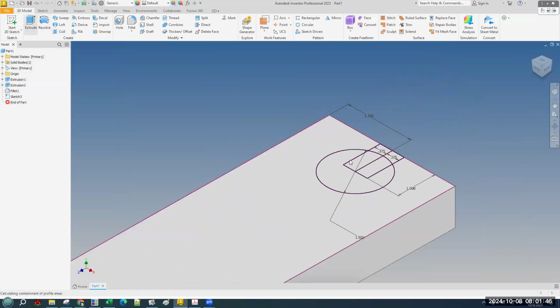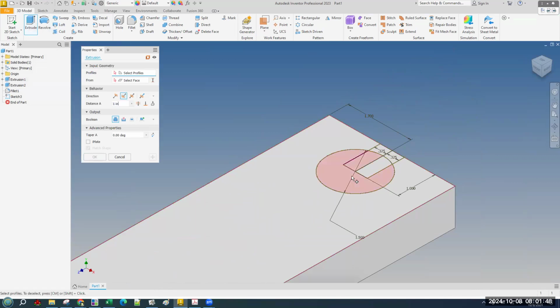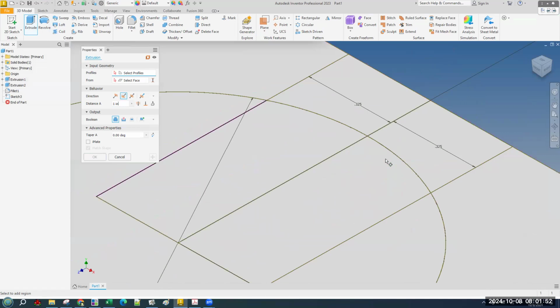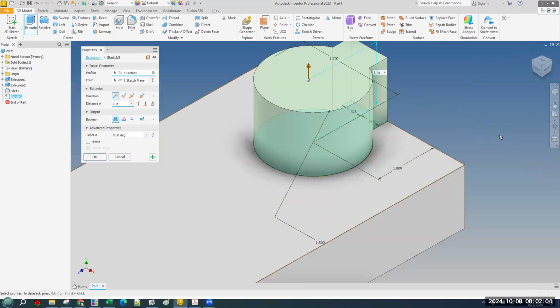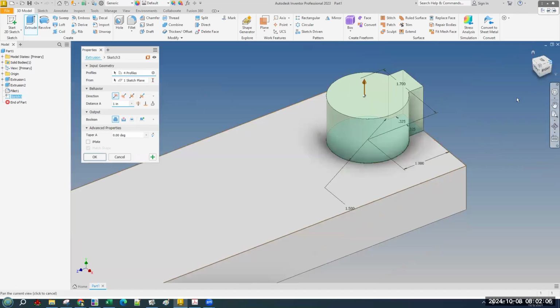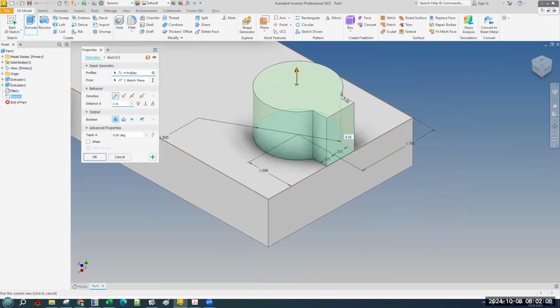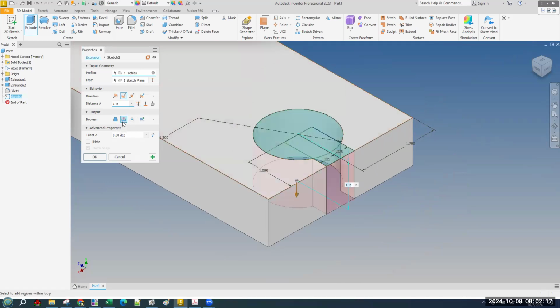Finish sketch, extrude. What's up? Excuse me, 0.325 in either direction. Okay, so we're gonna choose everything we made, and it will make you choose all the different parts. And once we choose everything we just drew, we don't want it to draw up. And also we don't want to create material. If we switch to cut, it will switch the direction.